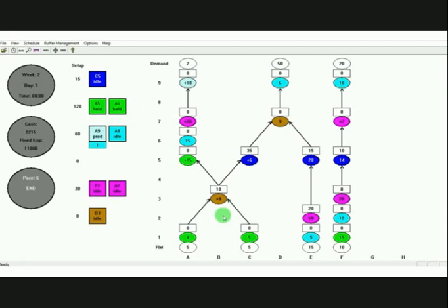The most expensive resource may not be that resource. The most sophisticated resource may not be that resource, or a resource which has got a very high changeover time, as we see here, may not be the resource which actually forces you to lose throughput. In this example, blue is the resource which gets most heavily loaded, and if you have a very nice plan for blue, you're going to succeed.